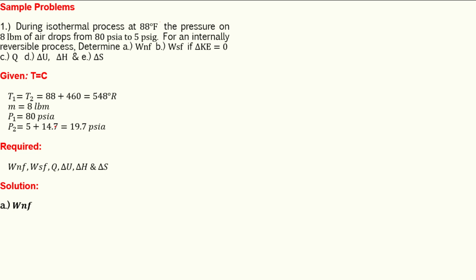From the formula we derived earlier, work non-flow is equal to, the given are M, mass, temperature, and pressure. So, we will use MRT ln P1 over P2. The formula you will use is based on the given of the problem. Okay, we have mass.